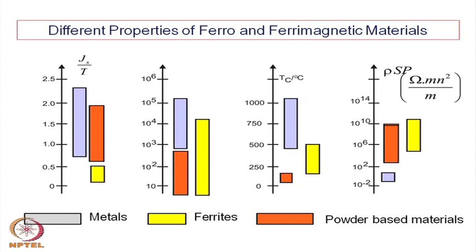So, that is the reason almost all transformer cores, if you have noticed, are in the laminated form, particularly the metallic cores, not the ceramic cores. Ceramic cores are solids, whereas all metallic transformer cores, iron silicon alloy in particular, which are primarily used in transformers, are always laminated, and then they are insulated also.